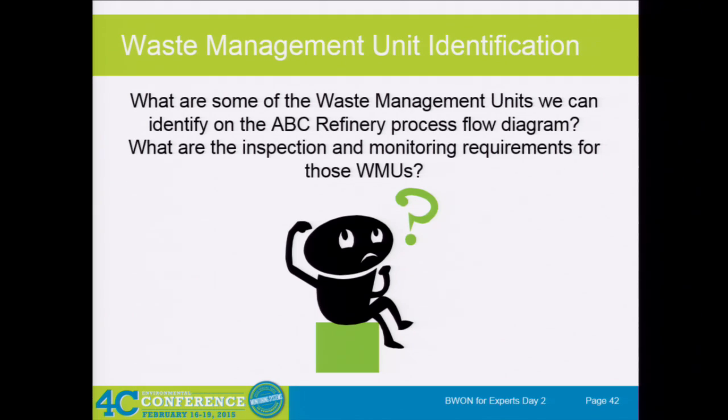Let's see, you've got 2 DAFs, so if we're looking at V9, that one is controlled. And DAFs are oil water separators here, right? So that requires both the quarterly visual and the annual NDE. Your other DAF, V10, is not controlled, so there's none there. Activated sludge unit, you do not do inspection monitoring there. But what do you have to worry about for an activated sludge unit?